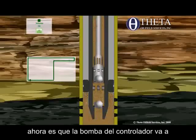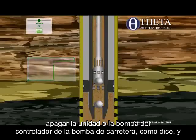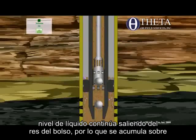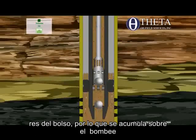Now the pump-off controller is going to shut the unit down, or the rod pump controller, I should say. And now what happens in the downtime? Fluid level continues to come out of the perfs, right? So it builds over the pump